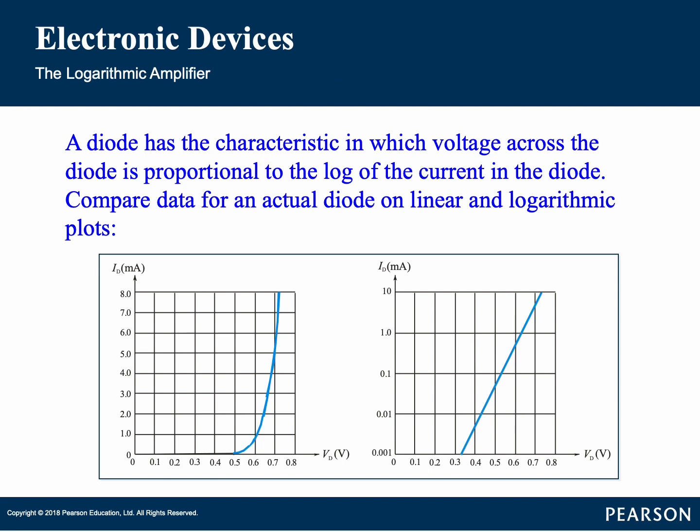Next is log and anti-log amplifiers. Both are used in applications that require compression of analog input data, linearization of transducers that have exponential outputs, and analog multiplication and division. They are often used in high-frequency communication systems, including fiber optic systems for processing wide dynamic range signals. The key element in a log amplifier is a device that exhibits a logarithmic characteristic that, when placed in the feedback loop of an op-amp, produces a logarithmic response.